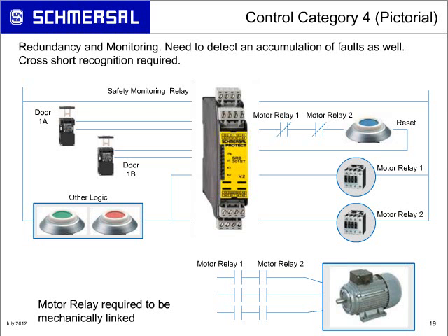When you use safety switches that use a mechanical actuator to change states and rotate cams, for example, or a safety-rated limit switch type of device, you don't eliminate the possibility of mechanical failure. What happens if a key breaks inside of the switch? Well, one single failure can lead to the loss of the safety function. With a Control Category 4, we can't allow that to happen.